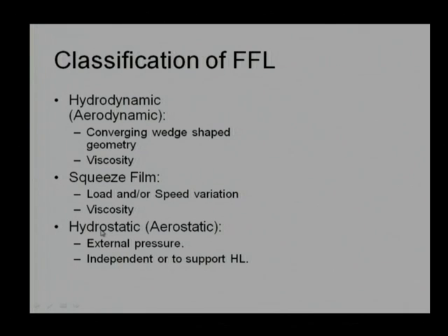The last one in this category is hydrostatic, and in bracket is written aerostatic. Hydrostatic is for liquid, aerostatic for gases. Here pressure is supplied; we need to provide external pressure to levitate one surface relative to the other surface.